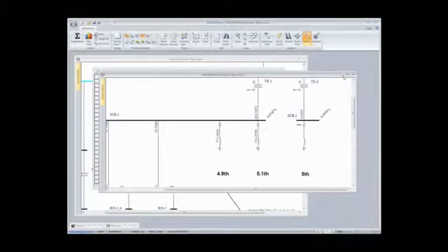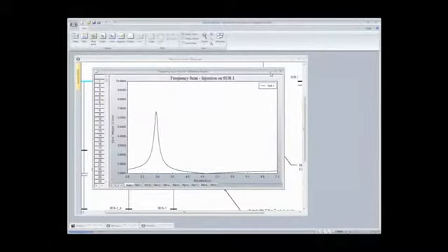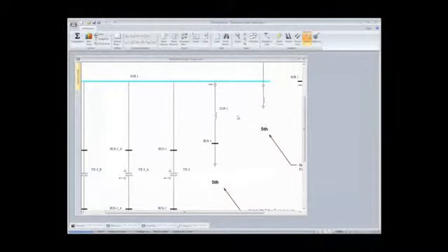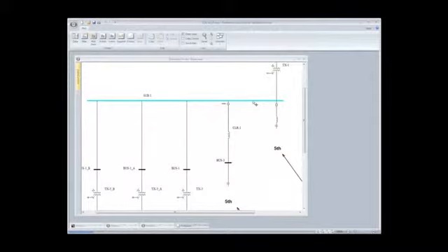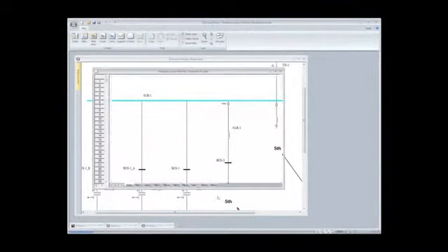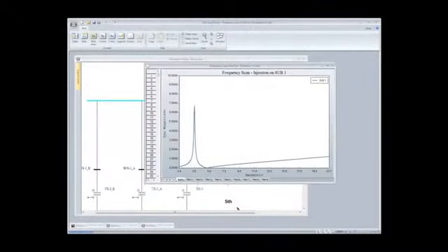We've got the interferential resonance case. Let's look at this distortion case here. I just wanted to show you where I have this broken out and where I have the single filter. If I do a frequency scan, and let me bring the plot up, I get exactly the same result. Here's our first parallel resonance sitting right about the third, which is not a good place. And then here we're tuned about the 4.8 or so.